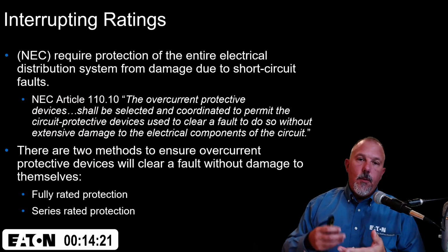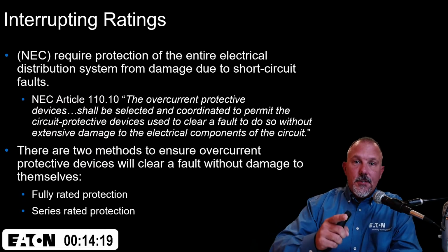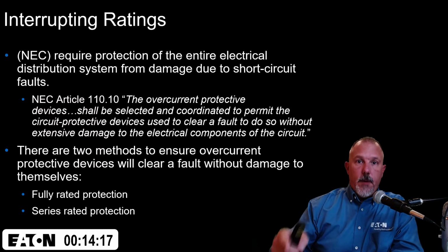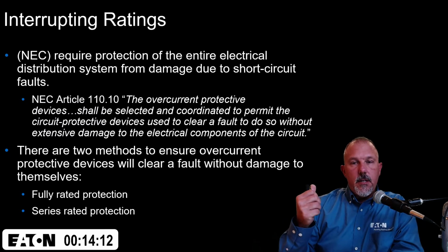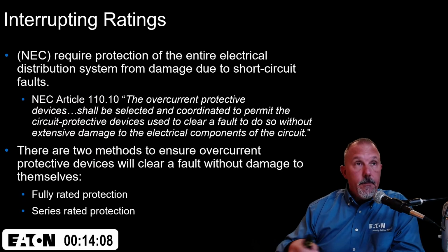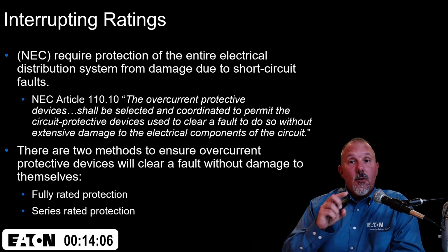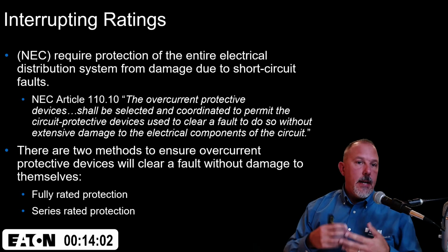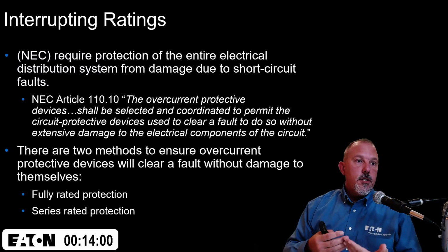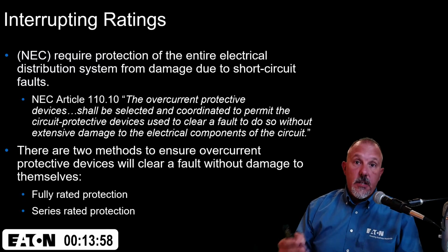Interrupting ratings. We talked yesterday about short circuit current ratings, and if you're not familiar with that, take a look at the 15-minute tech talk on short circuit current ratings that I did yesterday. Today we're going to talk about interrupting ratings and a specific type of installation. When we talk about interrupting ratings, we're speaking to series rated systems.